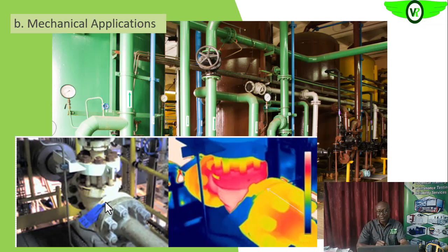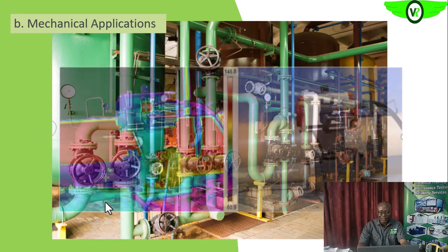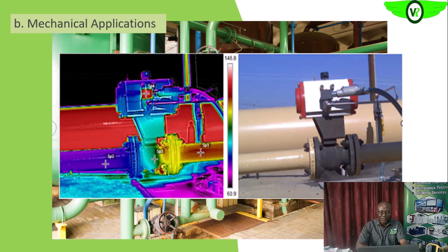Or if you shut and the stem did not move with the actuator, you will see that even if you have shut, the valve is still open. So it is possible that it will still be passing process fluid. So this is another example.